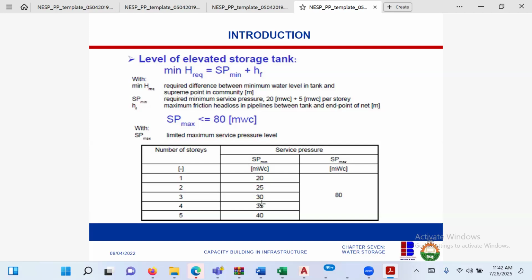of the highest person. In other words, if I come to a system and somebody is at elevation 300 and somebody is at elevation 320, my design will focus on the person at elevation 320. That means my tank will be at elevation 350, let's say, or elevation 340, so that I will supply the maximum pressure requirement to the person at 320. The person at 300 will already get water because the person is 20 meters below the person at 320. So if the person at 320 will get water, it simply means the person at 300 will also get water, but at a higher pressure.